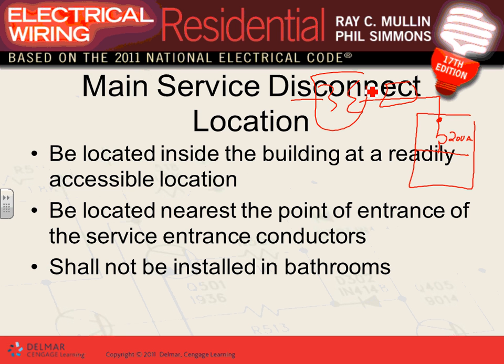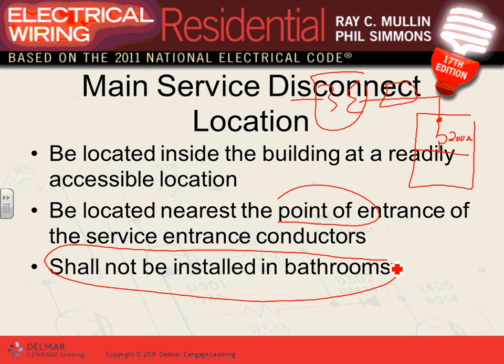Service disconnect means, that first circuit breaker, is so important. They call it service disconnect means. It has to have an overcurrent protection in it. This service disconnect must be as close to the point of entering the building as practical. It could be on the inside or the outside of the building. That's service disconnect means. As close to the point of entrance as practical, it shall not be installed in bathrooms. Can you put the service disconnect means in the bathroom? No.